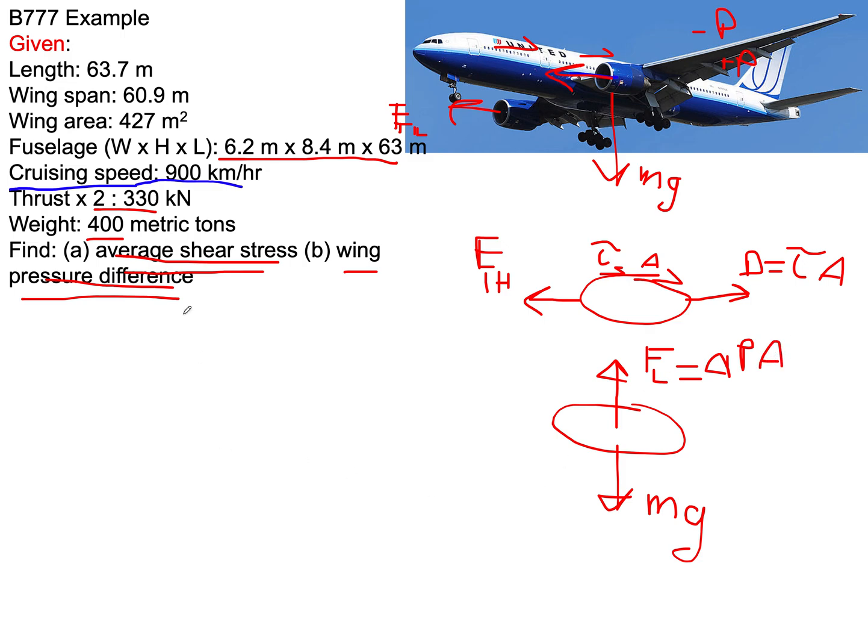So now this example is mainly to explain to you this cruising flight force balance. All the fuel that you put in to generate thrust really goes into friction, just goes to heat up the air around you. And the airplane is moving at constant speed. There's actually no work being done, because there's zero net force acting on the airplane, whether in the X or in the Y direction. There is no acceleration whatsoever on that body.